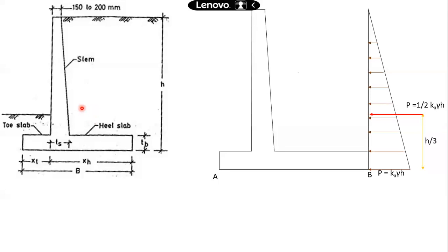Someone told about stability to avoid the overturning. That is also helpful to some extent, but it depends on which side you taper. Normally this tapering portion I want on the backfill side. On the front side, I want a perfect vertical wall. This will be hidden inside the backfill. I don't want any tapering or slope portion on the front side. That also helps in maintaining stability, because this tapering portion's weight, if you calculate later, we'll see will be very, very small. But it helps maintain stability, maybe to a very small extent.